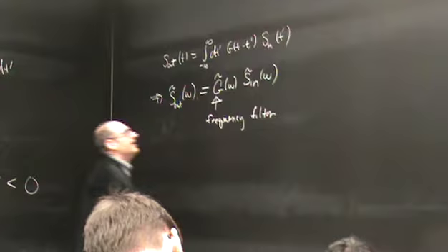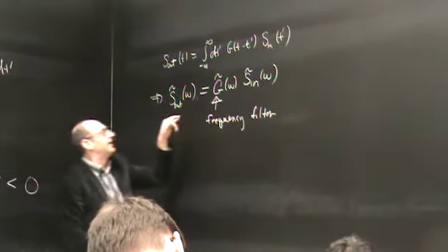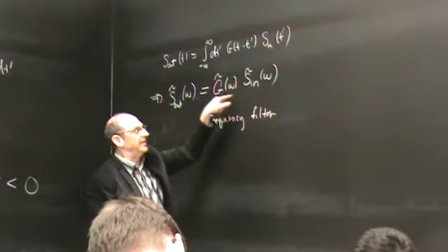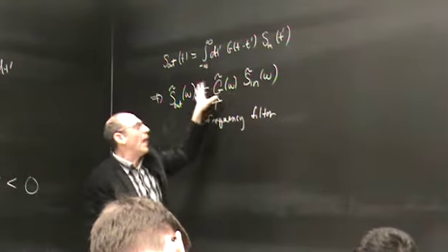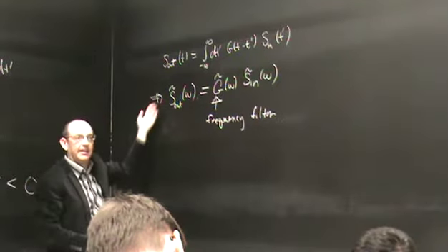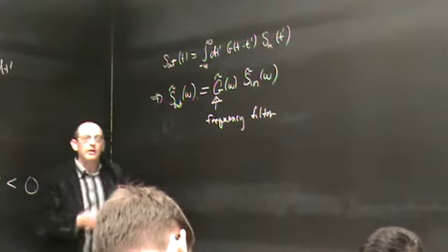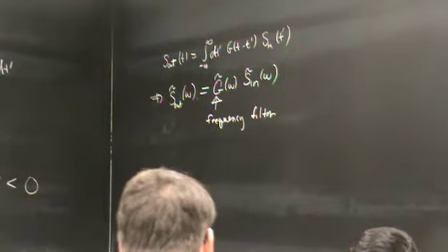That is to say, there's some frequency dependence of this G, and to get the output frequency dependence of the signal, I just take the input and multiply it by it. I can weight the input to get the output, and that's it. And then I can take the inverse Fourier transform. Okay. But now, we have causality.